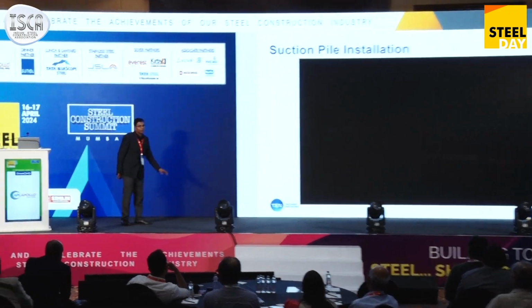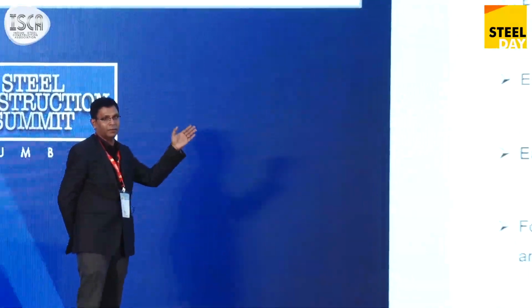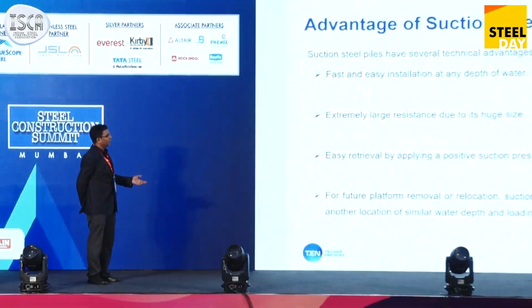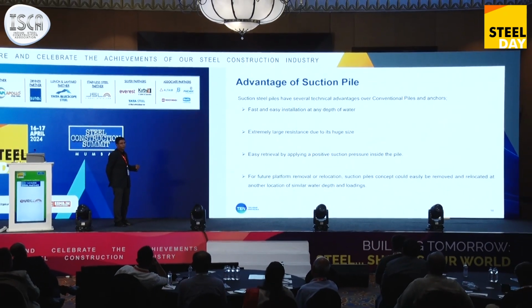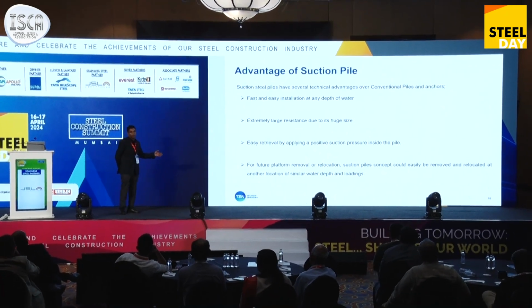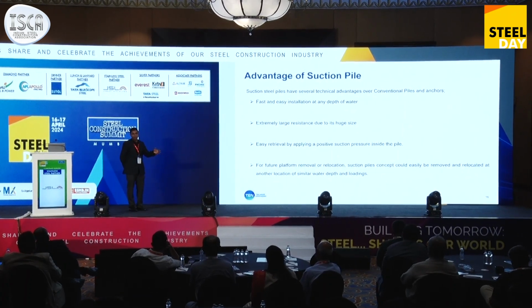Okay. Thank you. So this is how that suction pile installation happens. Now what are the advantages? Since as you see, you don't require any time for the installation, it is a single day operation, and based on the size of the pile, it has a large resistance as compared to a conventional pile. And one of the sustainability aspects is that this platform can be easily removed and it can be towed to another location with similar loading and similar water depths.